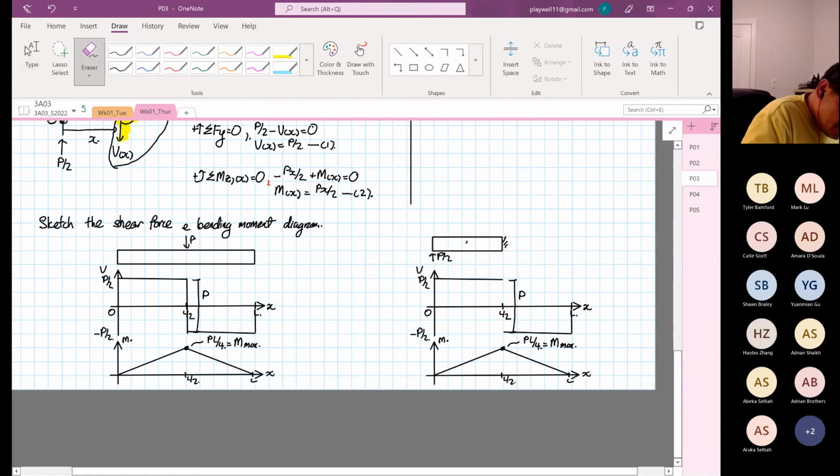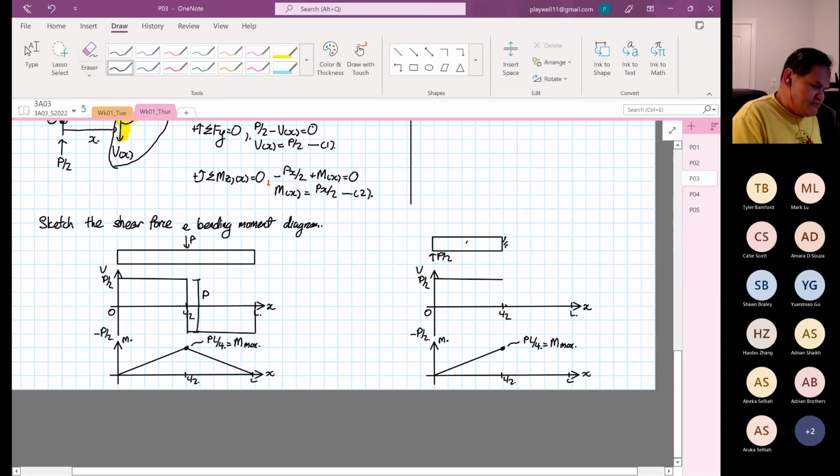So we know that this is coming down. All I need to do now is just delete here. That's all I need to do. You come down here, and then not come down, you stay down there. And then the other side, I just need to delete the other end. That's it, mathematically. So failure will occur at point C because bending moment is at its maximum.